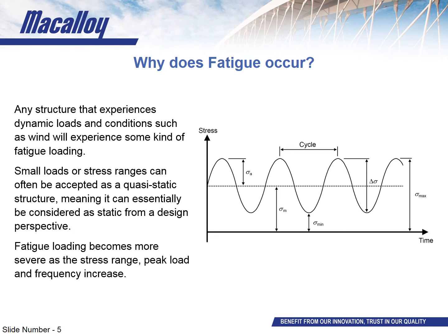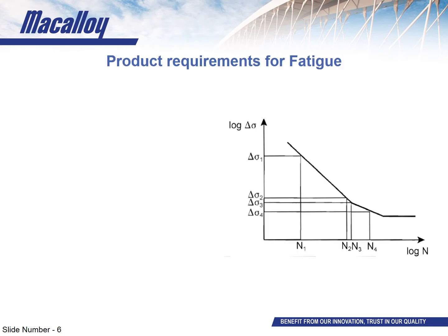Fatigue loading becomes more demanding on the structure as the stress range, the peak load, and the frequency at which it changes its load increases. Now, we'll talk a little bit more about where you can typically find that a little later on in the presentation. Now, unlike the last webinar, when I say tension rod, I'm not referring to architecturally exposed structural steel in this presentation. I'm using it just as a general term, meaning steel bars that are used in tension.